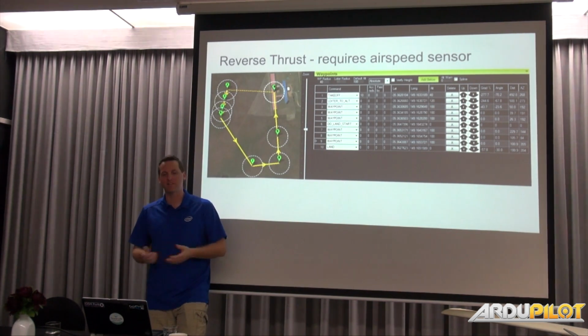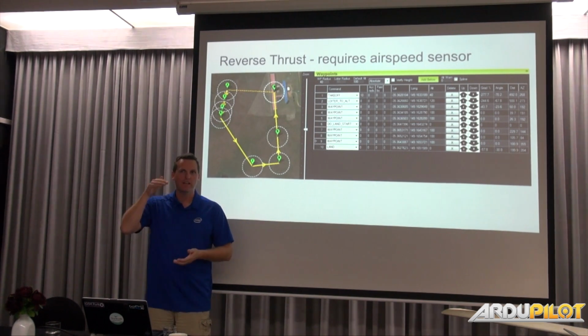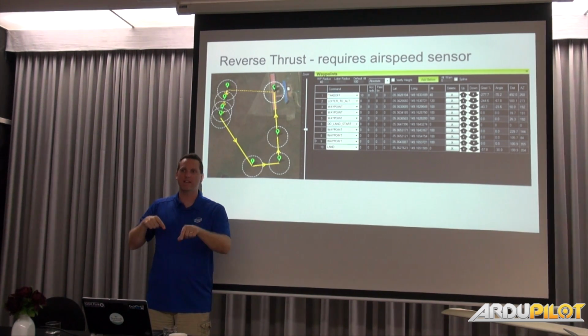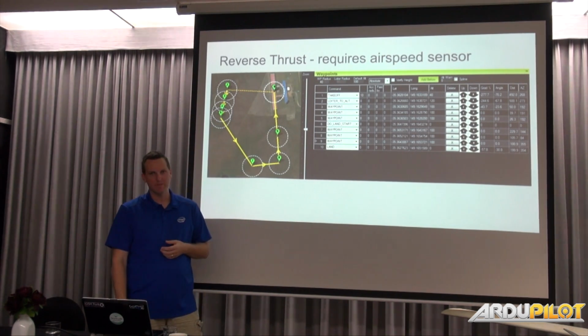And it just compensates. It's all airspeed, so it's all airspeed triggered. It's just trying to find a certain airspeed. So if you're going too fast, it says speed down until you reach that airspeed. And it's just hunting to figure out your airspeed to match.